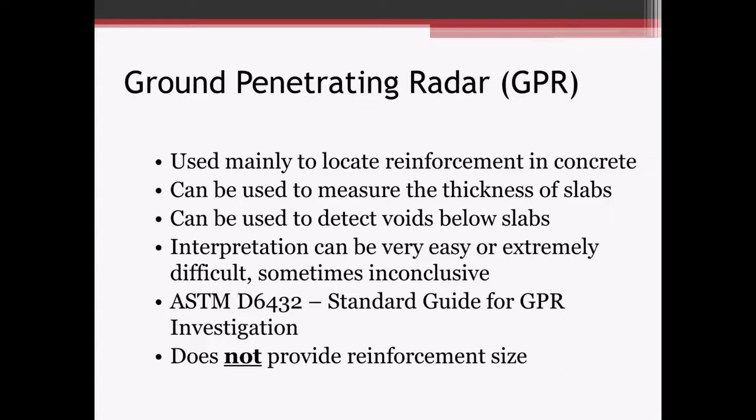You can detect voids beneath the slab sometimes, not always. It really depends on what the material is below the slab. Interpretation can sometimes be very, very easy, and other times it can be extremely difficult, and sometimes it's inconclusive. If you're looking for voids within the concrete or voids under the slab, it might be inconclusive. Sometimes you can say, yeah, everything looks good, but again, sometimes it's just inconclusive.